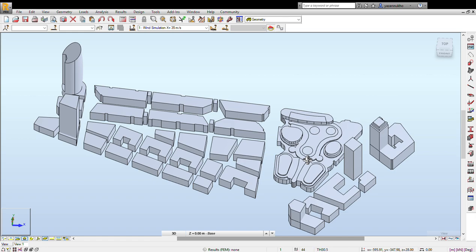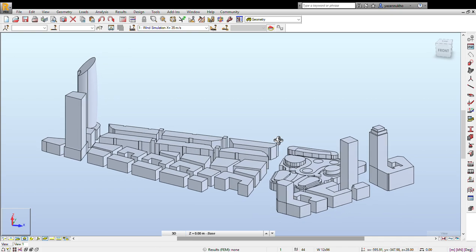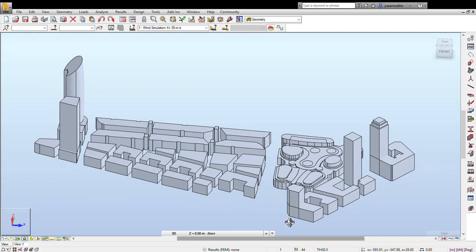We can build several scenarios, several case studies, and define either the velocity of that wind or the design pressure, which might be, for instance, 1.4. We can also build a special profile for the wind, identifying that the wind at, let's say, the first 50 meters height is 1.4, then it increases to 2.4 up to a height of 100, and above that it is, let's assume, 3 kilopascal.